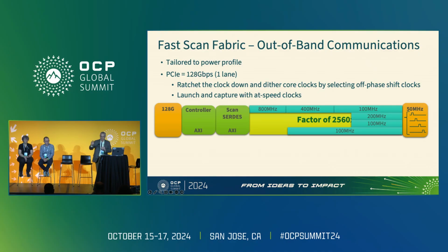But keep in mind that this pathway goes through the controller, through a piece of specialized DFT hardware to ratchet it down, and then through a special test fabric. That test fabric is basically a side channel or an out-of-band pathway from at least those green boxes to all the cores and other little things you're trying to test inside the design. So while you're doing test, you're really not messing with the other fabric. If you can envision using that fabric in the system to do testing in the field, you're not impeding the regular flow of data between these different cores. You're using this out-of-band fabric.